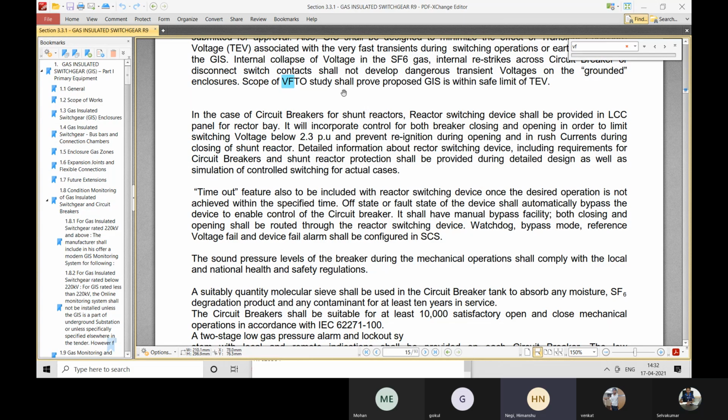You can model everything either as a cable or as a conductor. That's it. There's no other provision to model, for example, a surge arrester or how a surge arrester will operate. You can however model the transformer as it is, as three windings, or two winding or zig-zag or Scott connection or anything like that.